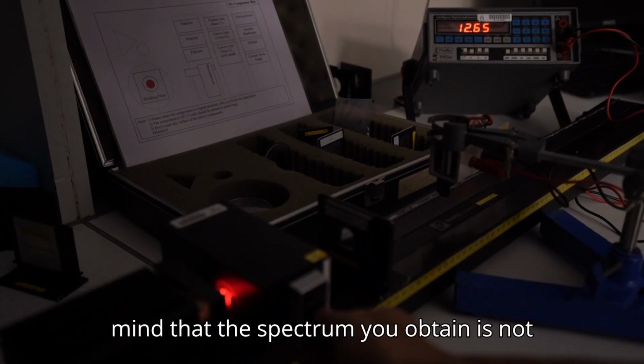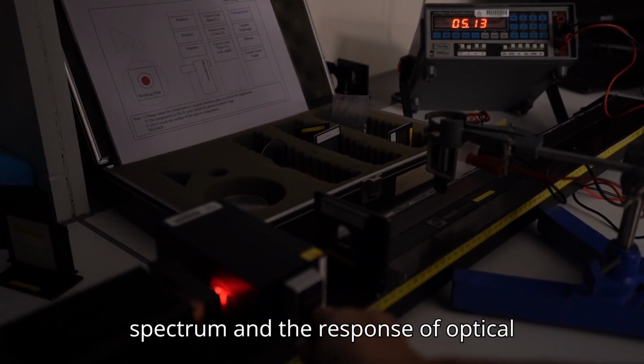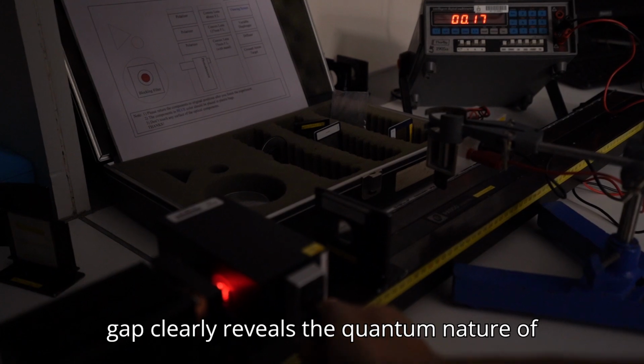Keep in mind that the spectrum you obtain is not just the intrinsic response of the photodiode, but also convolves the lamp spectrum and the response of optical components. Still, the sharp drop in photocurrent below the semiconductor bandgap clearly reveals the quantum nature of light.